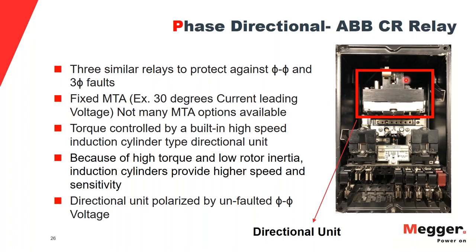Once the contact is closed, now my DOC is good for tripping, right? So this is employed because these induction cup types have low rotor inertia and high torque, so they provide high speed and sensitivity.